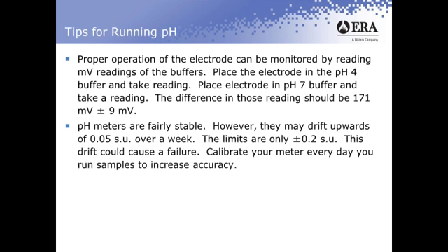So the second thing is pH meters are fairly stable. I'm sure as you've noticed as you're running it during the course of the week, they don't drift much. However, the pH meter may drift upwards of about 0.5 standard units over the course of a week.